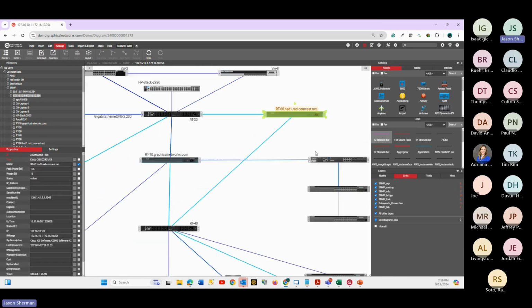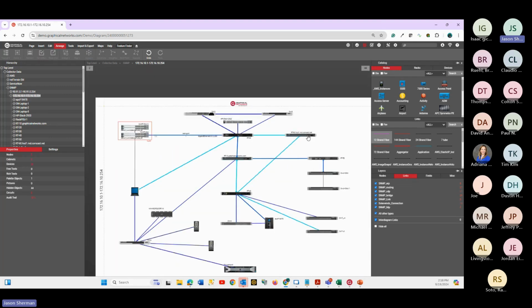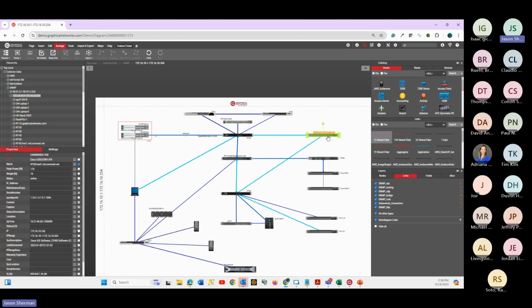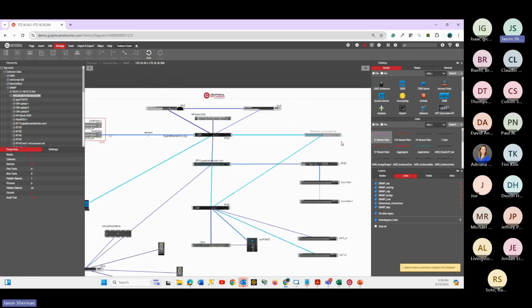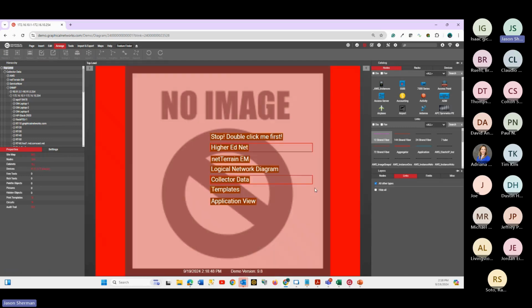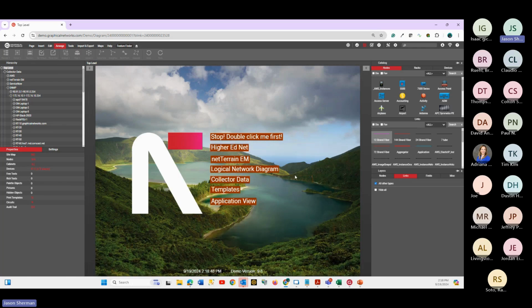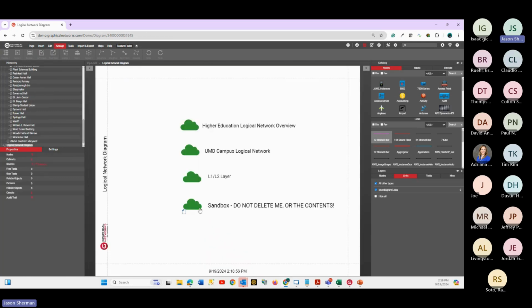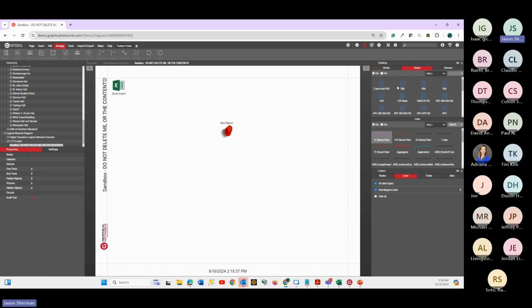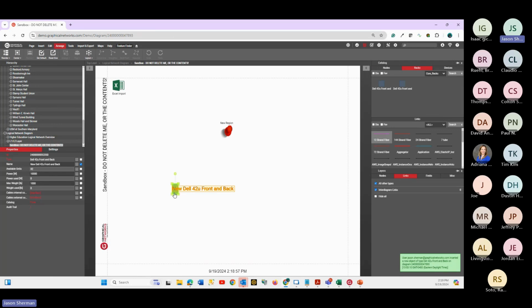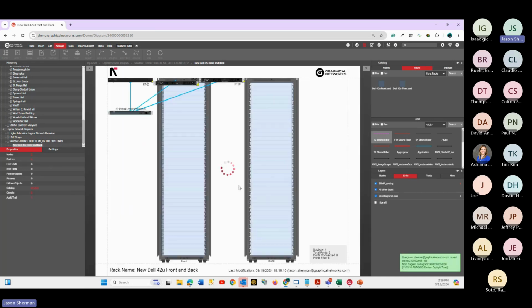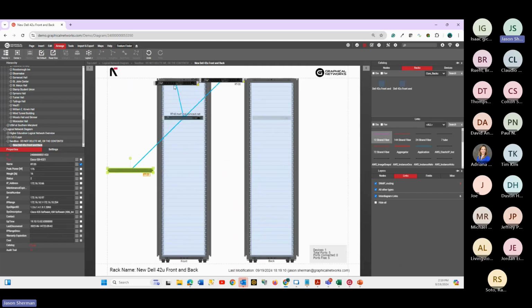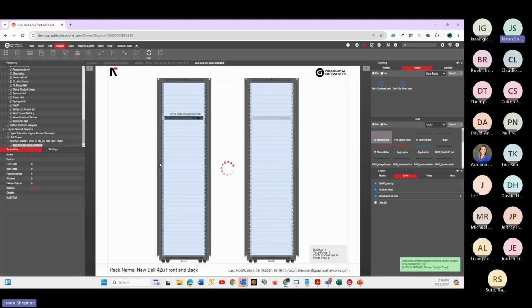Once the data is in a tool like ours, a network documentation tool, then of course you can lay things out. You can move objects around in the diagram. You can also take these objects and move them to another diagram. So for instance, I could cut this completely from a diagram and choose to put it into a whole other building drawing, maybe a logical drawing, or maybe you're going to build out a whole new cabinet. You want to document the cabinet. I'll just throw this down here. I'm going to double click on this guy here. And you're going to move the device over into this location. These other objects here are all reference objects, which we can turn off too if we don't want to see those. But if we do, we can keep those turned on.